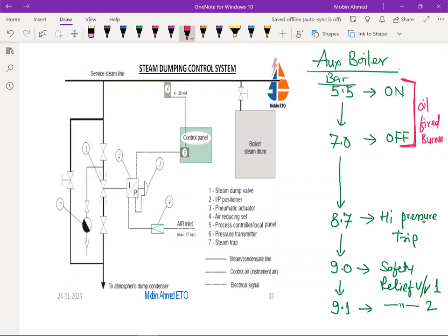And thereafter, when the ship is at sea, it is going to be the EGB, exhaust gas boiler. This is going to work. This is the mode, it will change over from here to here. Now, if the EGB is there, the main engine exhaust itself is 200 to 250 degrees centigrade when it is reaching the boiler drum.